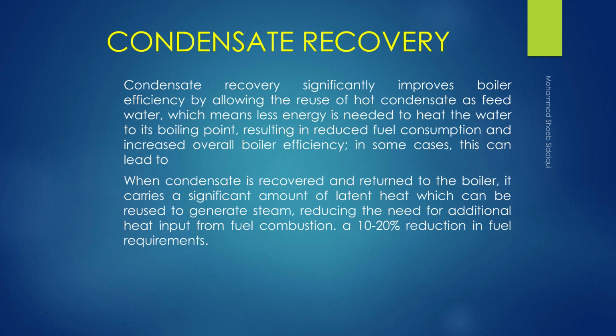Condensate recovery. Condensate recovery significantly improves boiler efficiency by allowing the reuse of hot condensate as feed water, which means less energy is needed to heat the water to its boiling point, resulting in reduced fuel consumption and increased overall boiler efficiency. When condensate is recovered and returned to the boiler, it carries a significant amount of latent heat which can be reused to generate steam, reducing the need for additional heat input from fuel combustion. In some cases, this can lead to a 10 to 20% reduction in fuel requirements.